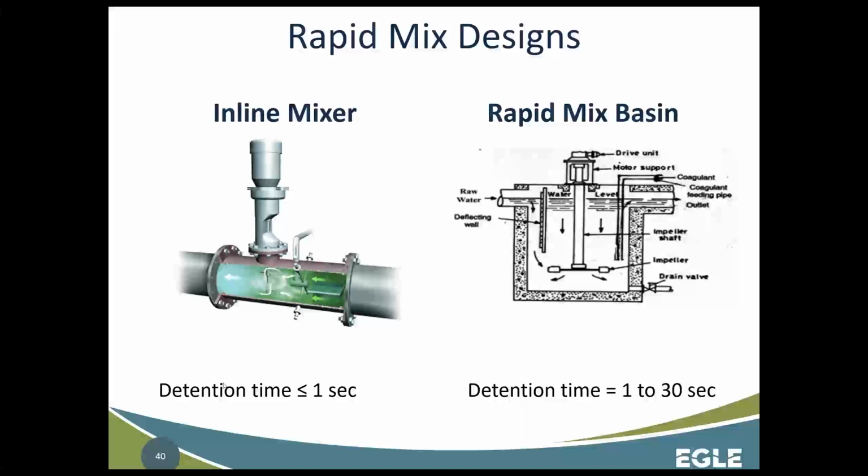The detention times are very quick. Here we're talking about less than a second. Here, maybe we're talking about 30 seconds. Bottom line is that the detention times for coagulation are much, much quicker than they're going to be for flocculation or sedimentation.